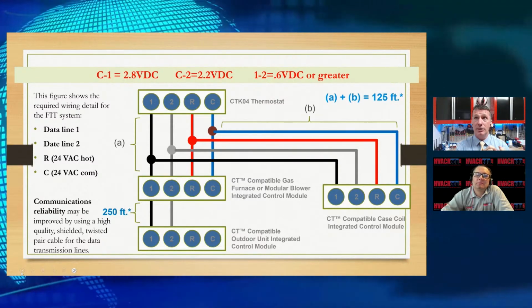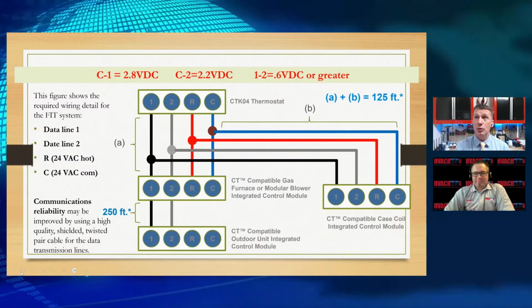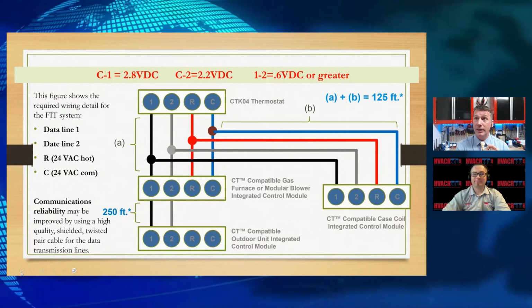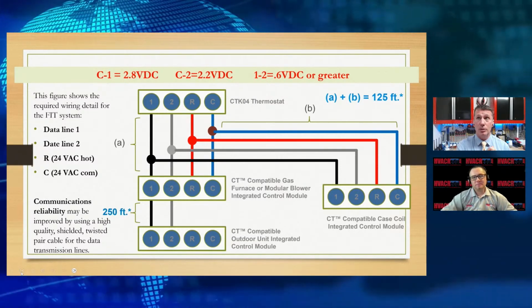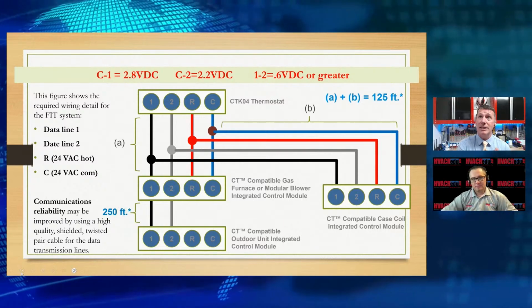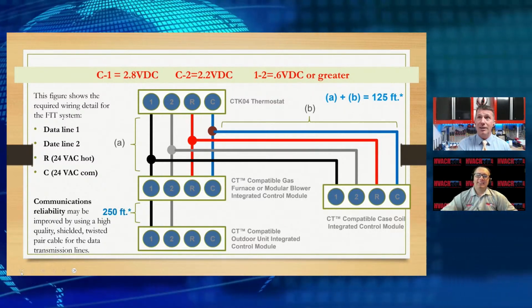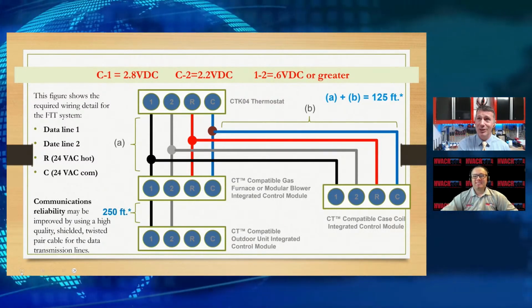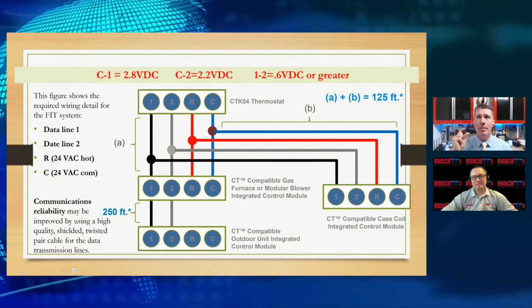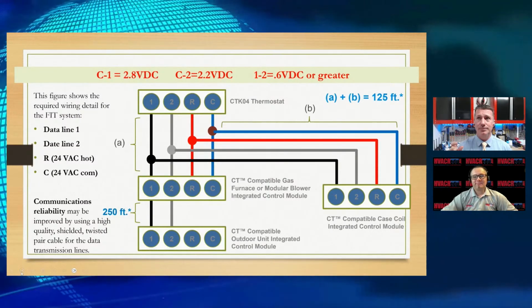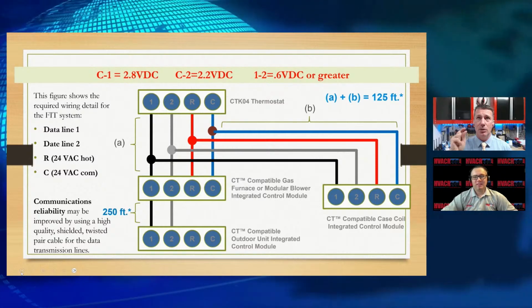You have conductors that are corroded because a mouse has chewed on them. You have conductors that have kinked or broken. You have conductors that are not landed properly on the terminals. You have wire nuts sitting outside from your existing solid wire that got water in them and corroded, and they no longer allow the communicating voltage because we don't have the amount of current that we had with AC. Very, very low current.